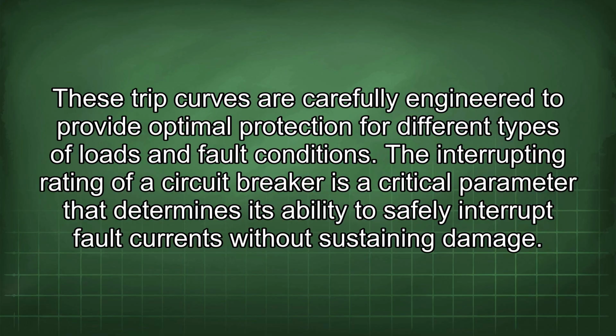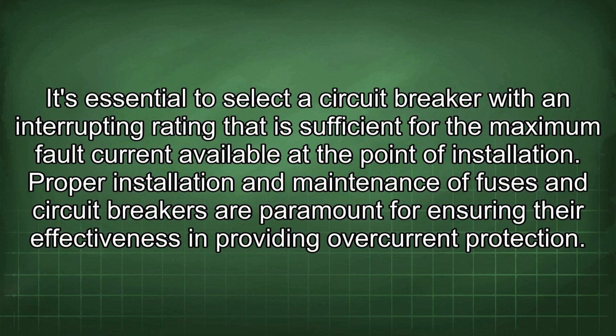The interrupting rating of a circuit breaker is a critical parameter that determines its ability to safely interrupt fault currents without sustaining damage. It's essential to select a circuit breaker with an interrupting rating that is sufficient for the maximum fault current available at the point of installation.